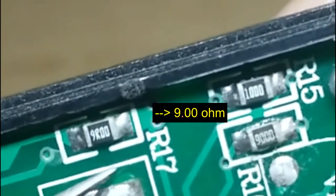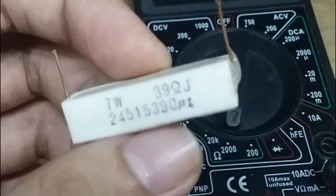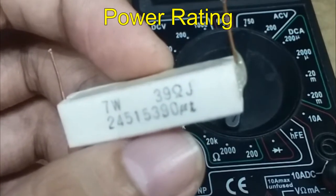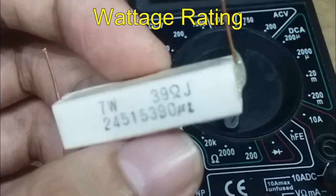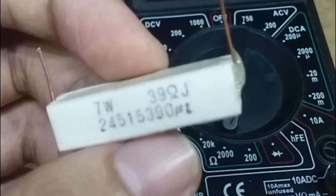resistor. But oddly, some resistors just directly mark the exact value, like this 39 ohms 7 watts, and that is the power rating. So resistors have a power rating or wattage rating, so when you use a resistor, be careful not to exceed its power rating.